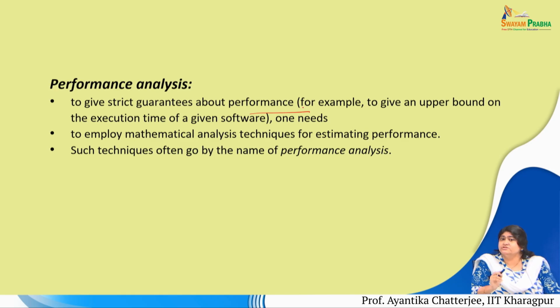Now, the execution time of all those instructions should have some upper bound, and the effect of those executions, like if it is finally giving some input to some actuation, then all these tasks should be completed within a certain deadline, and that deadline bound scenario must be validated or verified through this performance analysis, employing mathematical analysis techniques for estimating performance.